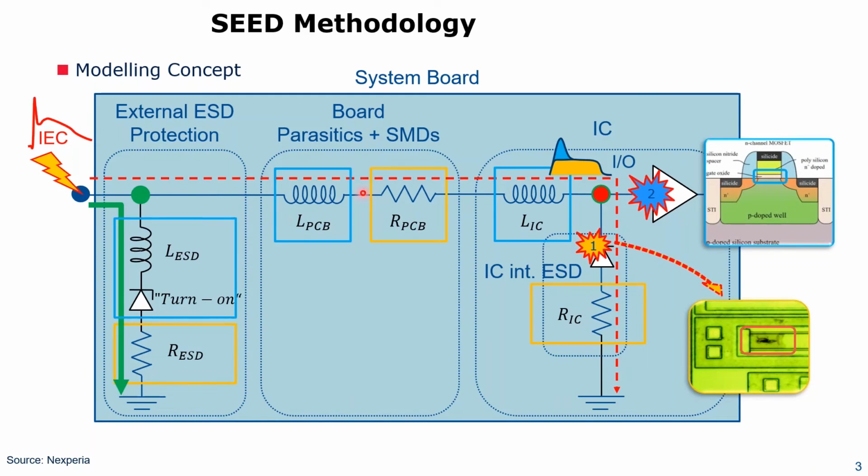This is shown for positive voltage. It's also true for negative voltage. In the design, it's really critical that we clamp the voltage very close to the signal voltages, and we have to make sure that in the turn-on race, the external turns on faster than the internal. If the internal turns on and the external tries to turn on much later, then there's no voltage left for it to turn on anymore, and the IC will be destroyed.